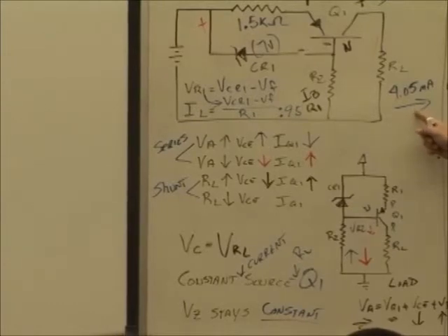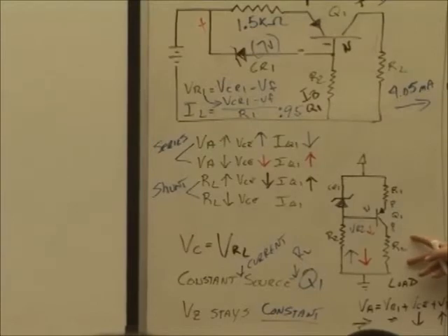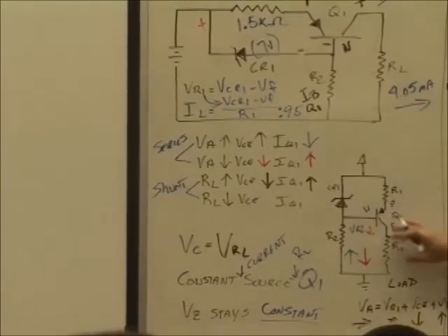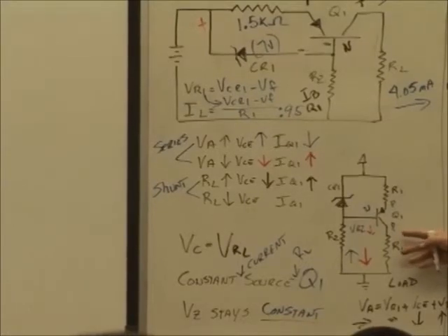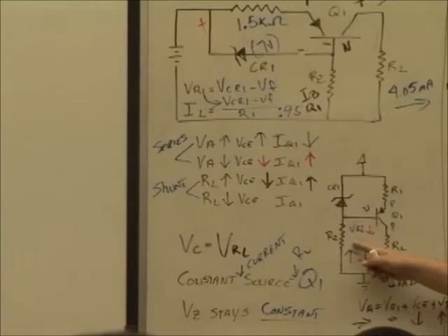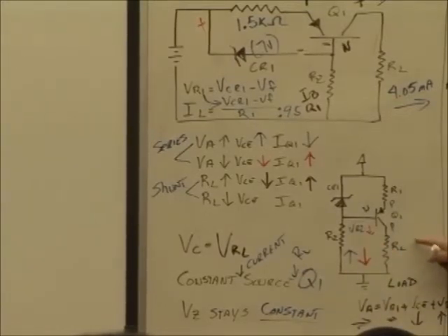Remember, this is a current regulator. If I make this load larger, what's going to actually change? The load voltage. So think about the load voltage. Because essentially, when we're dealing with the load, the I total's the same, isn't it? If I put a larger load in here, obviously some of that current's going to go over this way, isn't it? So how this circuit compensates, it's essentially the same current. Load voltage is going to go up, VCE goes down.